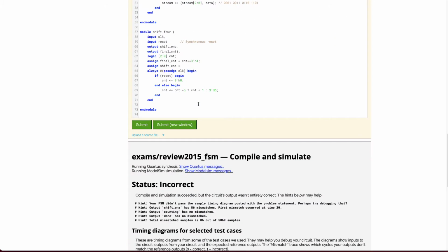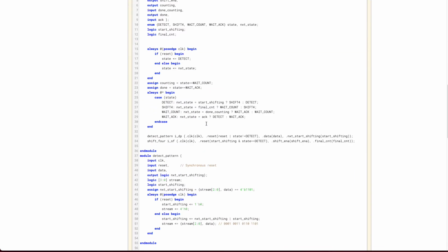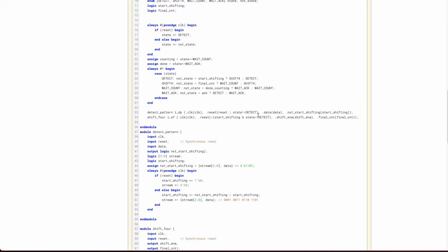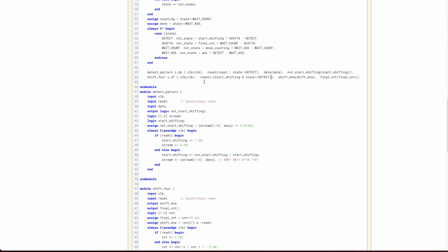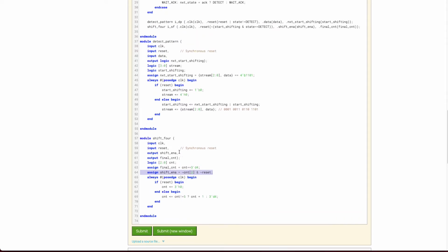So this stops reset. Stopping reset. Actually, I don't need to do all this then. So reset is always 1 unless we're doing the state transition. So if reset's always 1, this is always 0, and then if we do the state transition, then the next cycle starts. And when the next cycle starts, we're going to count from 0 to 3.